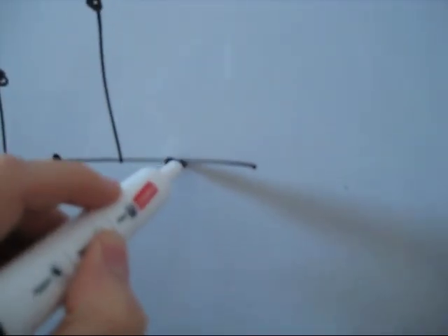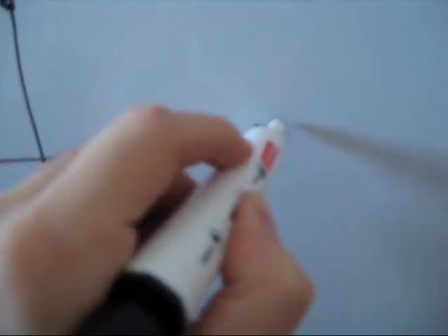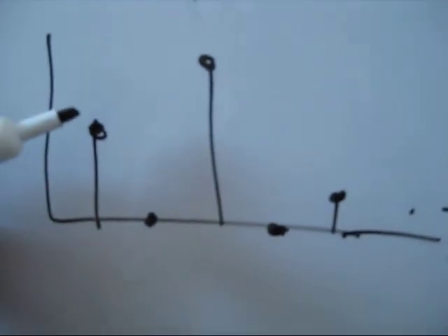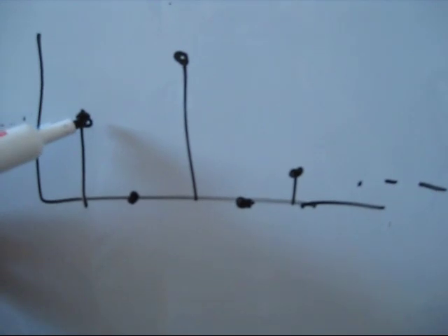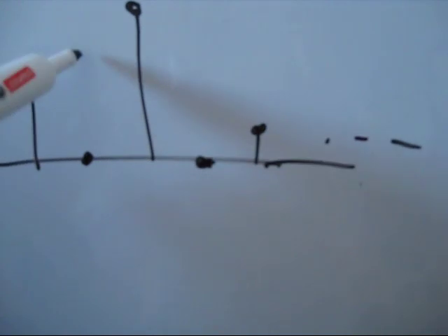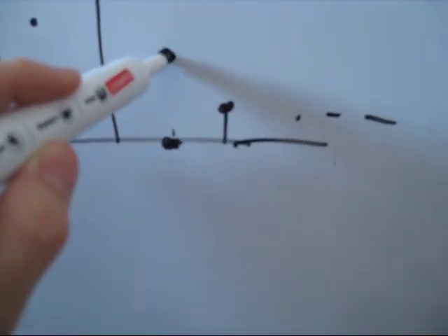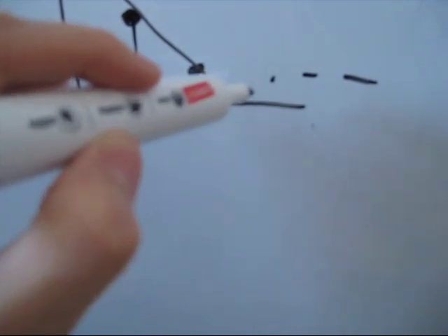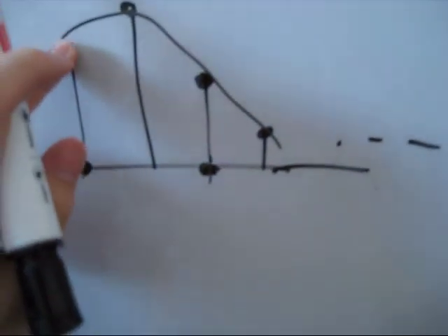Now you need the gain of L because if you actually go through and you do the math and whatnot, you'll find that the amplitudes have shifted. Like, if you think about it, if you take your data points, I'm going to draw this yet again. Data point, gap, data point, right? Blah, blah, blah. If you were to take this and low pass filter it, you're not just going to bring these points up. Like, you're not just going to bring this up to here and this up to, say, here or something like that, to make it all nice and smooth. You're going to end up actually doing something like this.